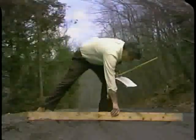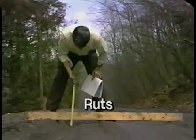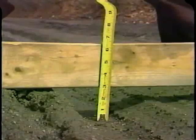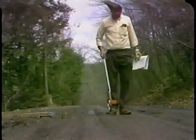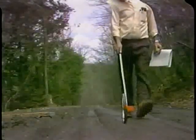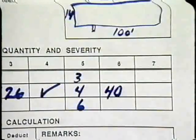Again, using our straight board and tape measure, we classify ruts. These ruts are about 3 inches deep, so they're of the medium severity. And with a dimension of 4 feet by 10 feet, we record a total area of 40 square feet in the medium column. If there are ruts of any other severity, we record the total area of those as well.